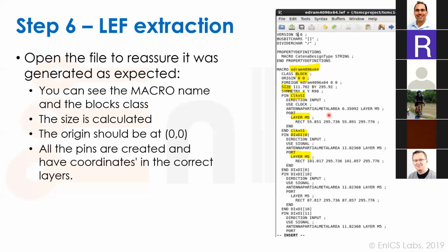So one of the macro providers was not including the antenna information in the LEF. That's very important to make sure. The risky thing about LEF is that you encounter real problems very late, because LEF is an abstraction. When we do a physical sign-off, things start popping up, but the problem is it's 3 weeks before tapeout, and then you tear your hair.